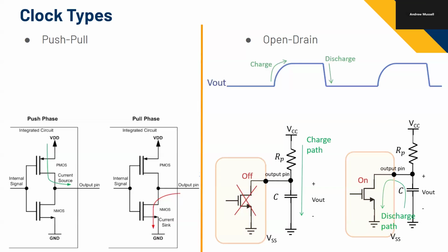That's what's limiting the speed of I2C, because you have the RC charging for the rising edge and it's curved, so you need to wait for that to settle. And the more you want to increase the edge speed, the lower your resistance needs to be. But the lower our resistance is, I'll show you how to calculate the discharge path.